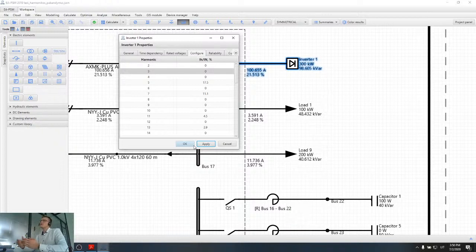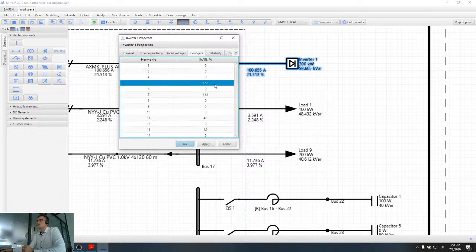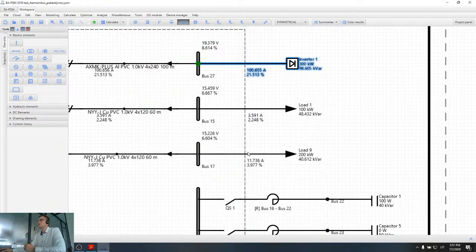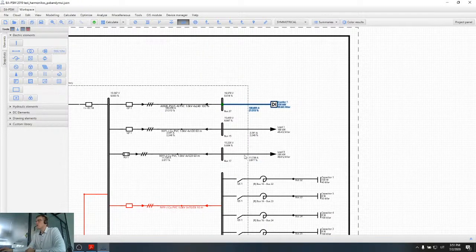However, during today's training, I won't concentrate more on this harmonic, which is more common for administrative buildings, like also shopping malls. I will concentrate more on harmonics that exist in industrial networks, like production plants and also distribution networks, because those third harmonics are very small in distribution networks. In most cases, they do not exist in the distribution networks at all. So one more example, and after that I will also check your questions.